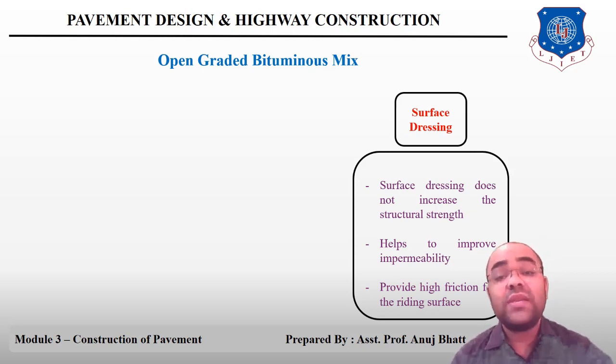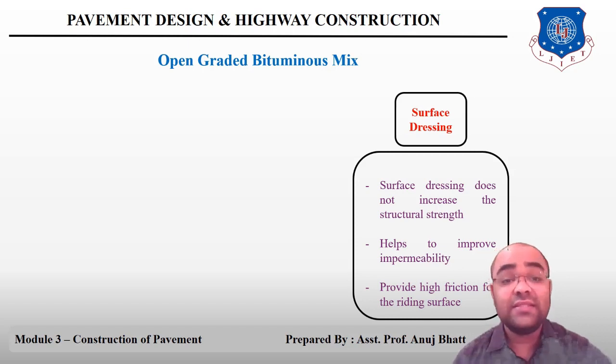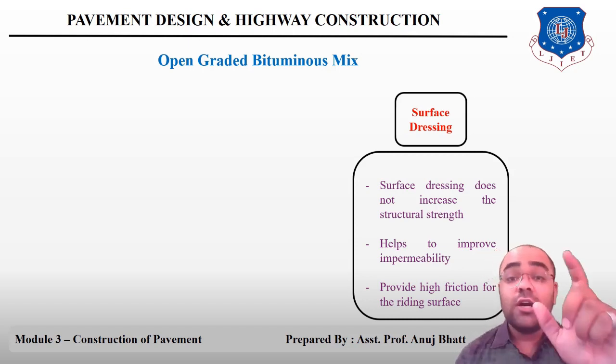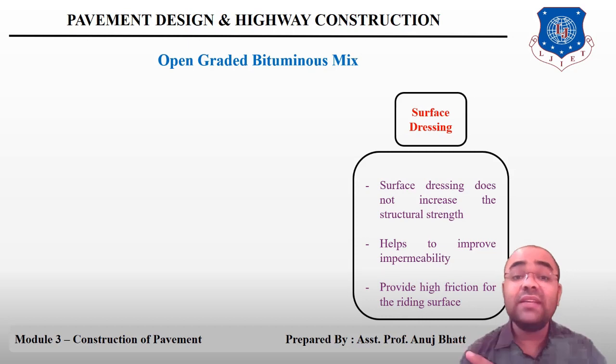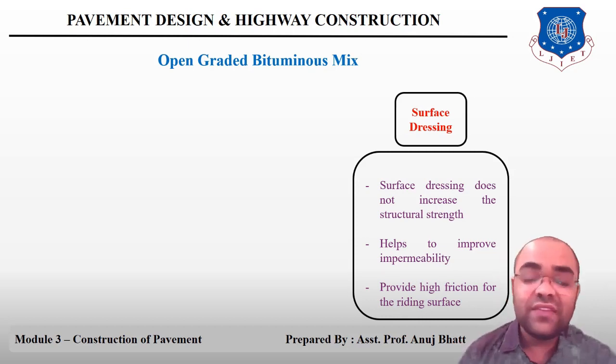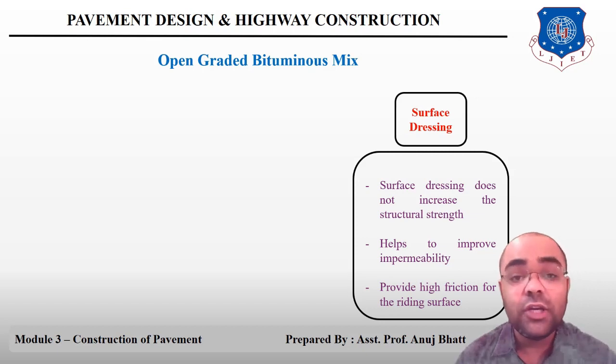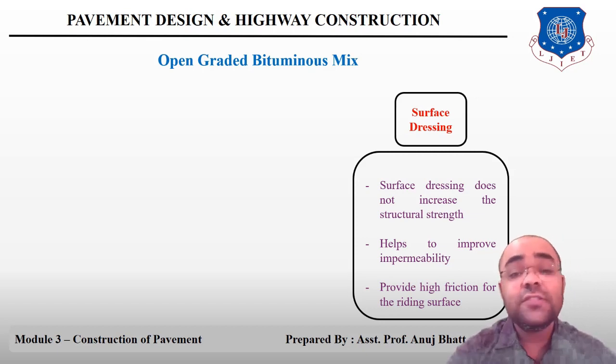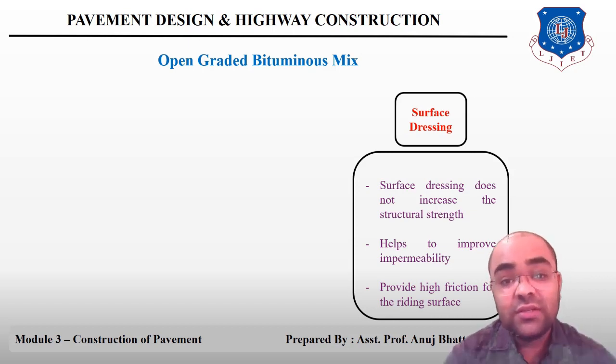This particular bituminous mix, surface dressing, does not increase the structural strength. If we talk about the significance or the objectives of this mix, surface dressing will provide a dust-free wearing course. It will help in providing impermeability against water percolation.